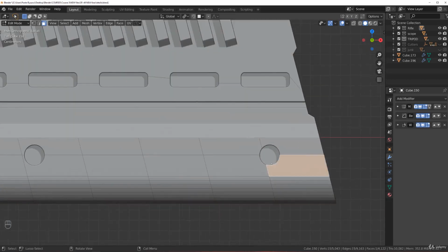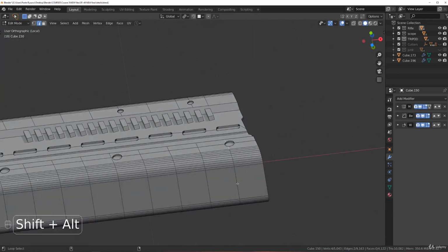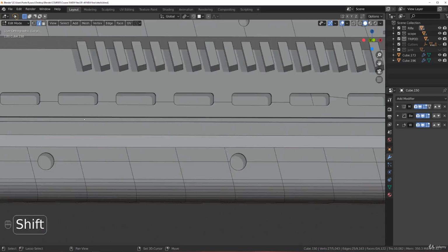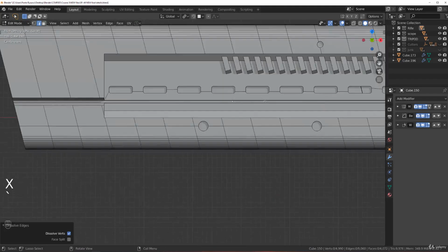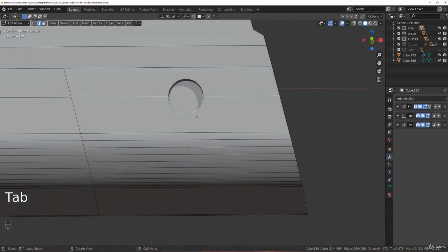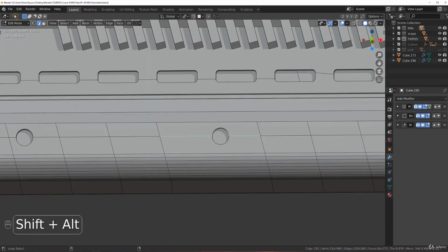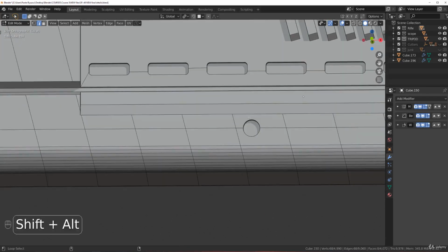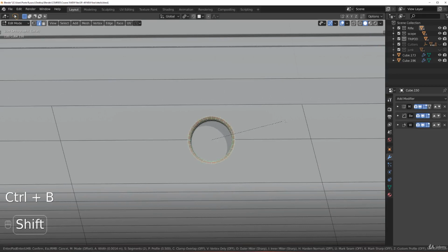is we don't really need this. Okay, we don't really need this. Let's remove that because it's gonna actually cause havoc with the bevels. So let's you know what, let's select these. That's fine. And let's remove this one, select these, let's remove this one, select these, and remove these ones. And we might be able to bevel them, I mean we might have to bevel them differently.